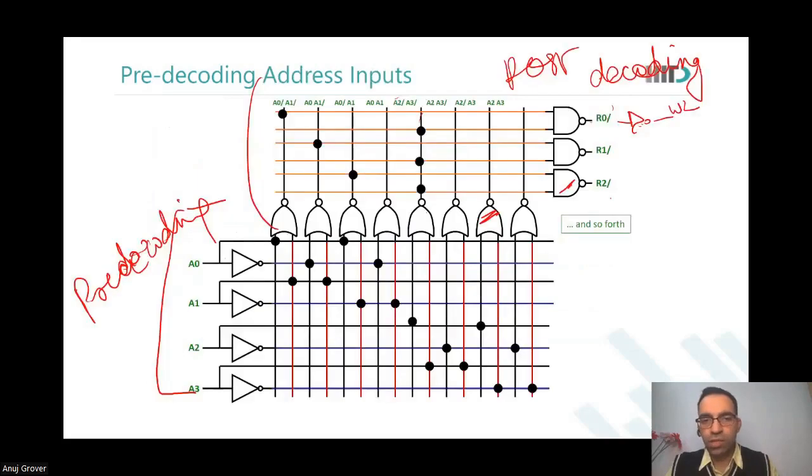So you see over here, each output of these post decoders, like if I consider this bus of the first pre-decoder, only one of the outputs of my pre-decoder connects to any one row decoder, any one post decoder. Are you able to see this?